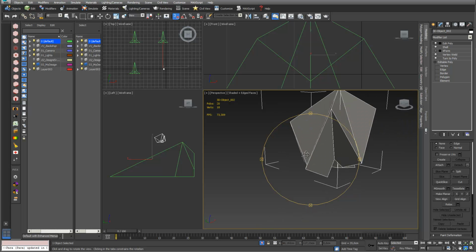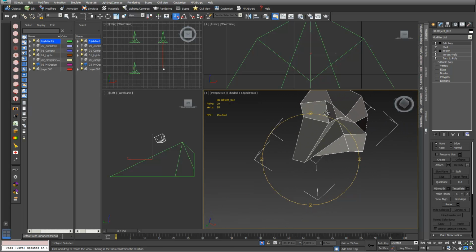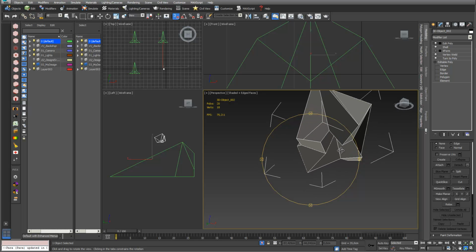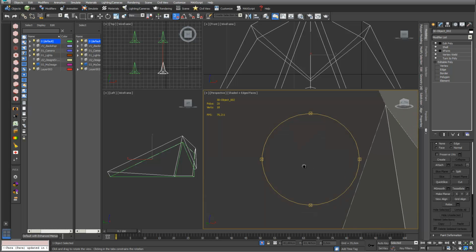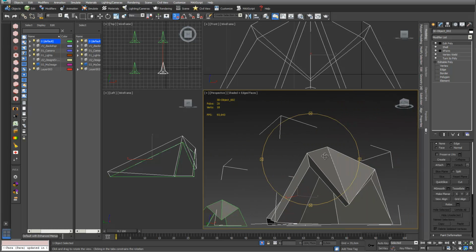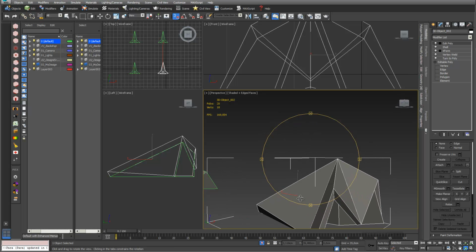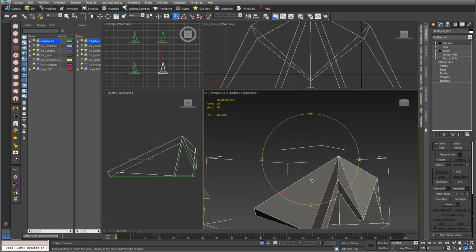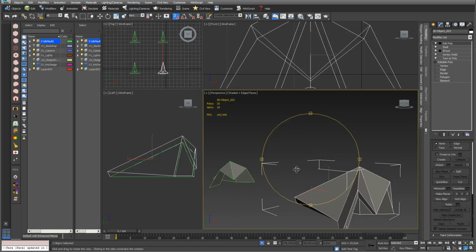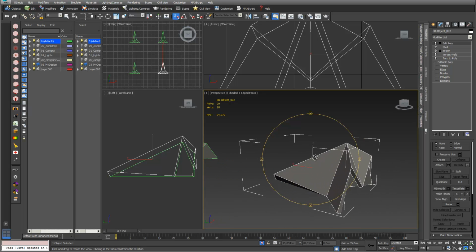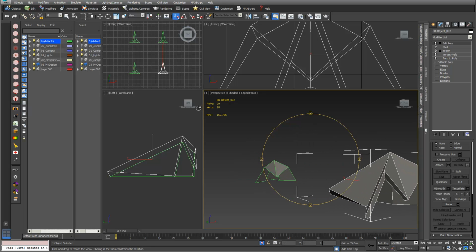then you see that something happened. The dimensions are definitely not like 4 centimeters anymore. It's completely too thick because it's still related to the scale of 1300 something. So you have to use the XForm underneath or on top of your Shell function for it to work properly. Always, if you scale something and the Shell function looks weird, then use the XForm underneath, and it works better. Okay, so that's the first method we can use.